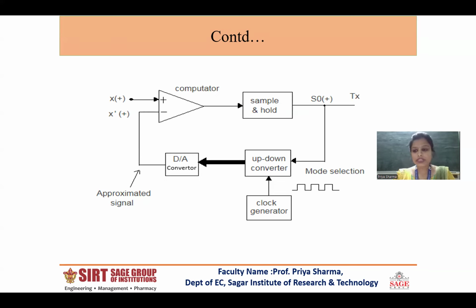How can granular noise be reduced? When an alternating sequence of ones and zeros occurs, the digital to analog converter automatically reverts to its minimum step size. Thus, granular noise is reduced.